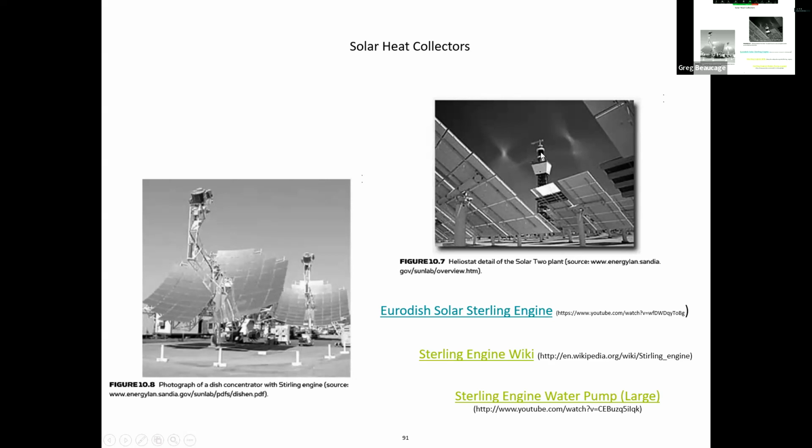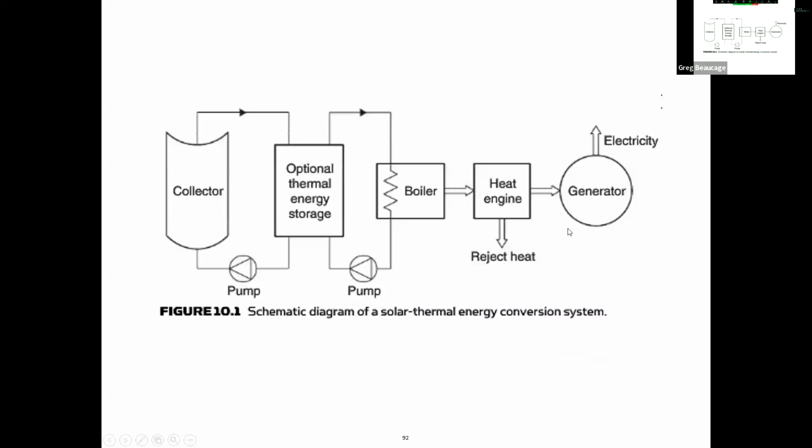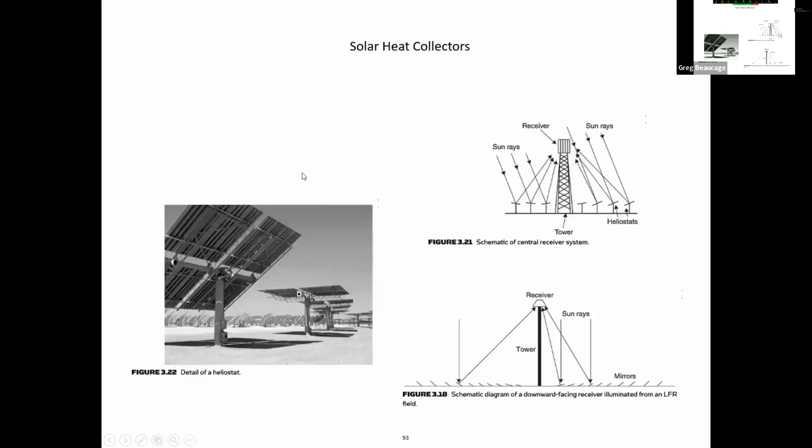This gets to like 2,500 degrees at the top, and then the salt goes down, and at the bottom there are tanks that store the molten salt that are insulated, right? Then you run water through those tanks and it boils, making high pressure steam. That runs into a steam generator, and you just make electricity with that. So basically, it's a coal plant after the thing there, right? So these are pretty large.